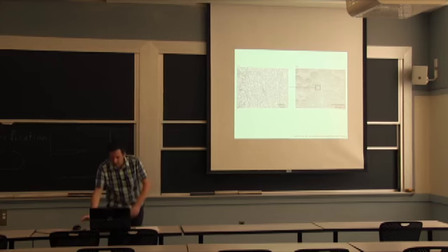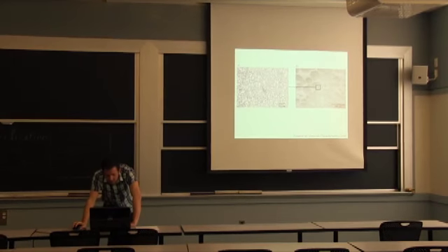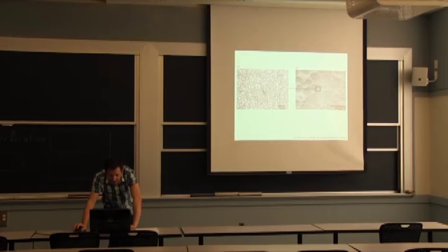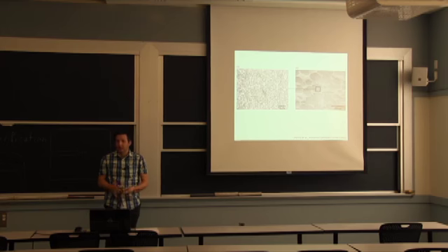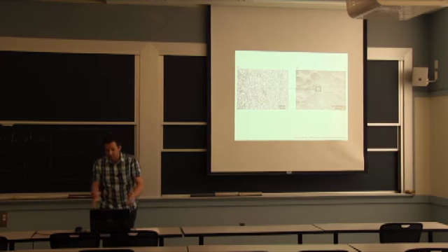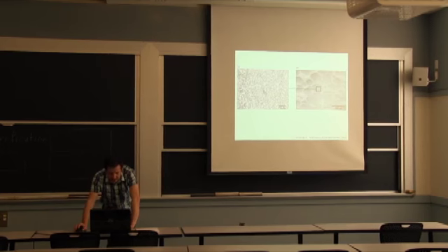The tungsten carbide here are the particles. You can have them in a very granular shape, and here you can see you've got some big ones, some small ones. There's some idea where doing it this way, you have the small one fitting into the big ones, and you can sometimes reach a higher particulate density than if everything is the same size but crushed like these ones here. The binder you see better in this phase here.